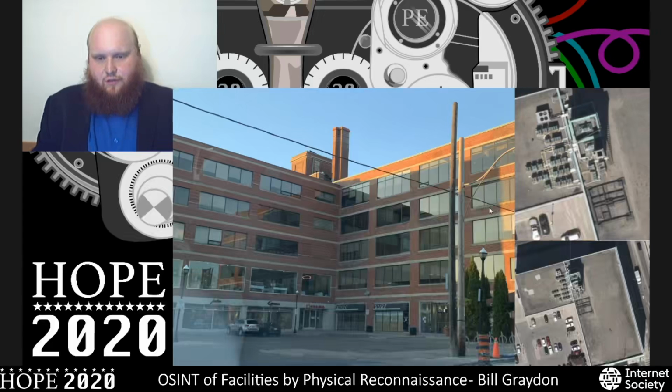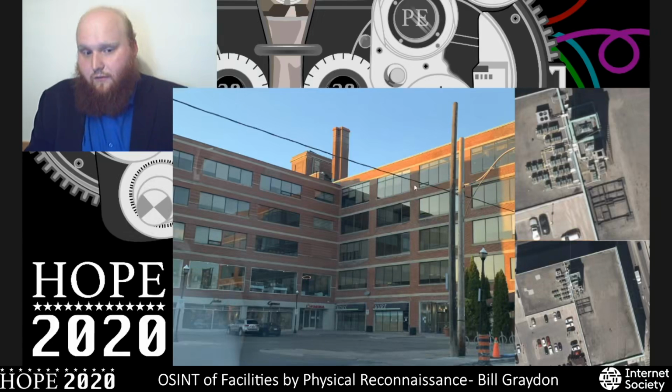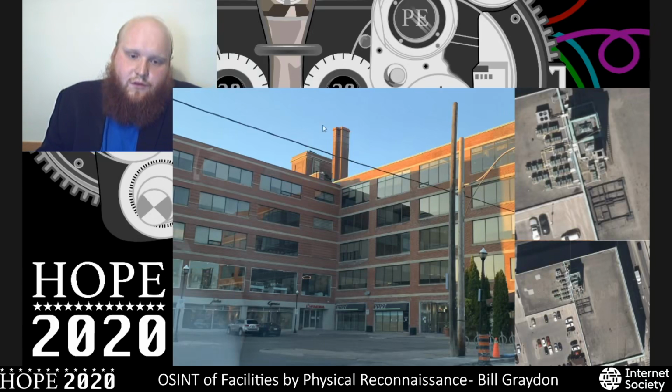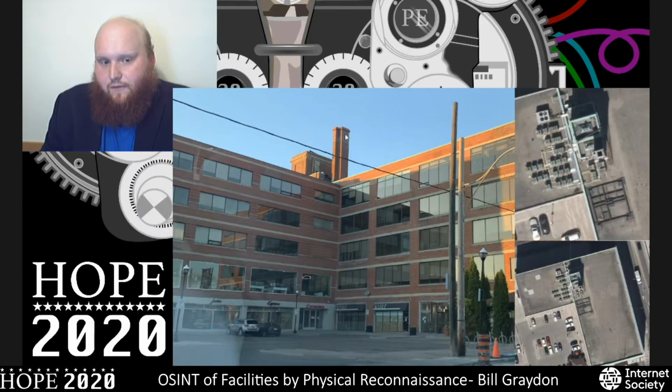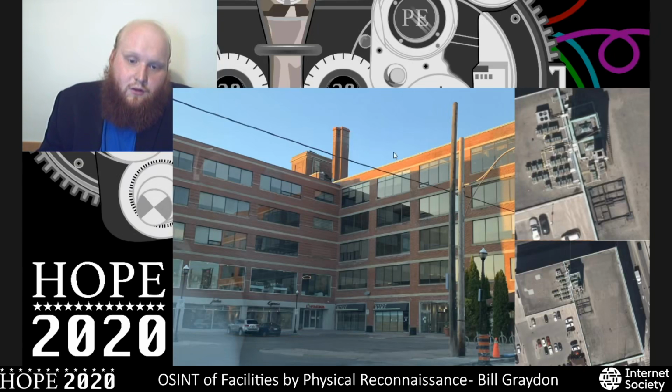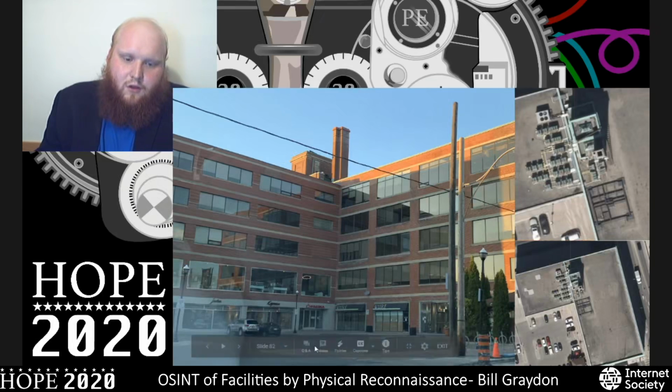This is a really, really great case study. There's a lot we can tell from this particular set of pictures. So looking at this building, the first thing we'll observe is this large chimney stack here, which indicates that the furnace is somewhere below it. The furnace could be in a mechanical penthouse, but we see that there are none on this building by the fenestration. It could be below ground.